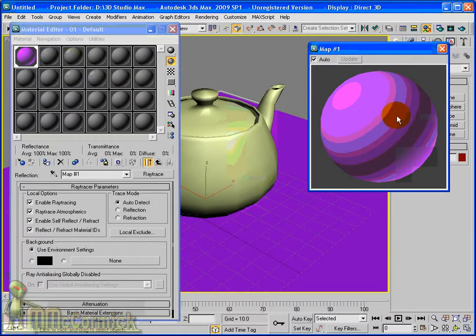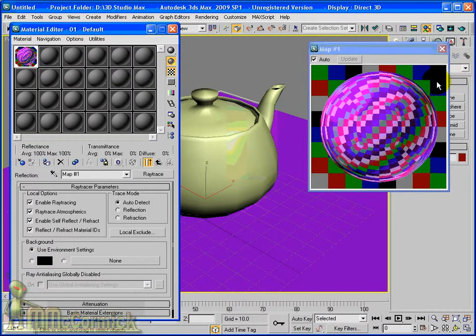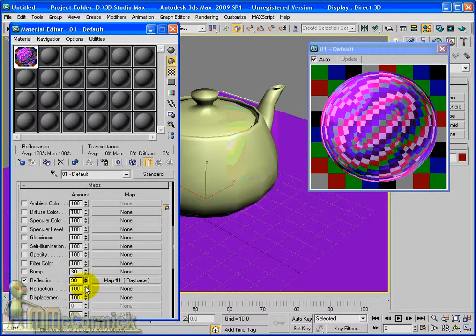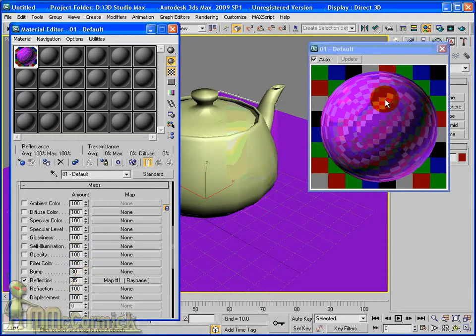We can't really tell how reflective this material is just yet, but you have this checkered background. So if we click on that button, you get a checkered background come up, and the object in the middle, you can see how reflective it is. So back up to the parent and we can reduce our reflection. You can see how this is reduced in our material. So let's add that to our plane, give it a quick render.